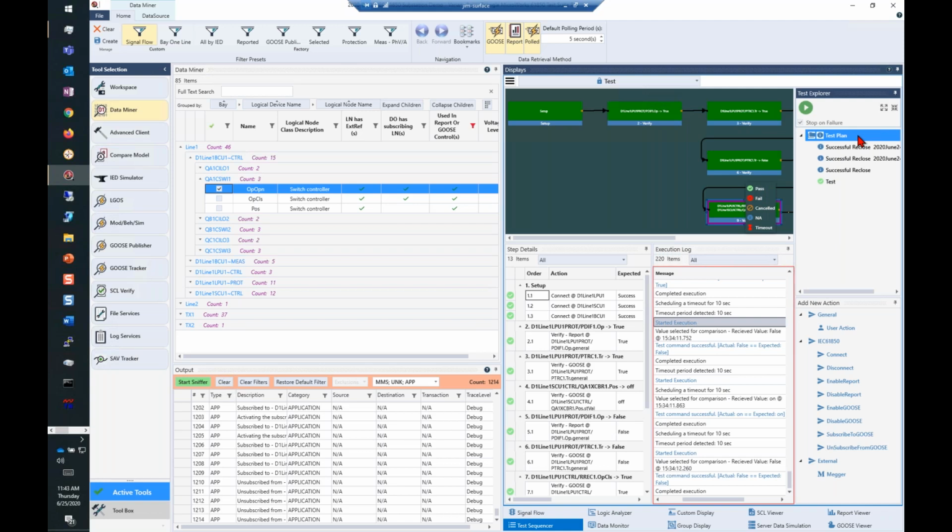So for the respects of can you continuously run it, you could just re-add the same type of test to the point where you've got 10, 15, 20 of them. And that way you can vary the exported results to make sure, over time, is your test consistent? Are you getting the same results each time, or is something varied? Yeah, I think what we might want to do is add a configuration on this where you can put a counter. So if they were doing burn-in testing in a heat chamber, you could execute this test repeatedly 100 times or something, so they could run it overnight. And that test would keep running, and then give you the results in the morning.